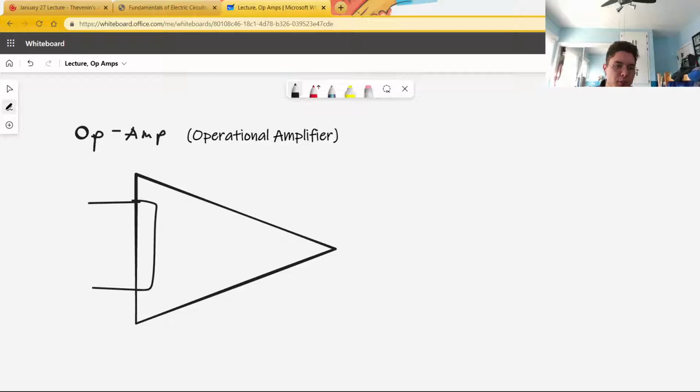In the ideal world of an op-amp, these two points are maintained to be at exactly the same voltage, which makes sense because there's no resistor between them. Additionally, however, the operational amplifier attempts to ensure that no current whatsoever goes through this wire either. Typically, it does so by having an extremely high resistor right here. Because the resistor is so high, current is very unlikely to go through it, and if very little current goes through the resistor, then there must be a very small voltage drop through the resistor. A voltage drop which is basically zero.